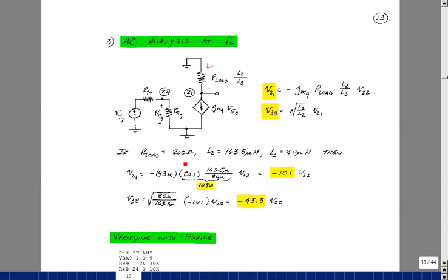Now, if the load were 200 ohms, and this again is not exactly the value we get in our radio, but just something in that neighborhood, and I measured the values of the inductances on the transformer, and I figured out the dots using supplemental problem 1.19. So using these values with my value of gm, I'd predict a gain of about 101 out of this amplifier stage. And what would show up at the output of the transformer would be a little bit of a step down of that, to a gain of 43.3.